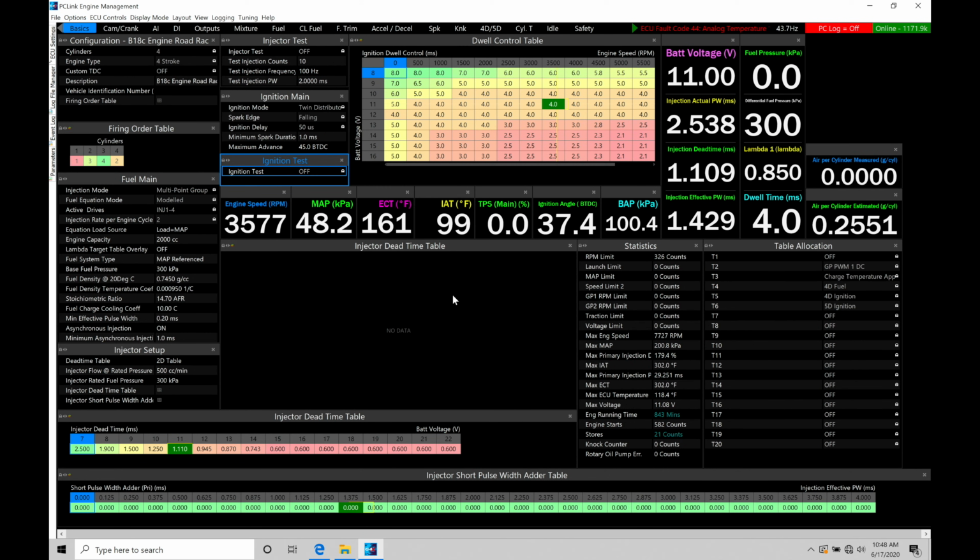So these failsafe protection features are in place so that the engine won't get damaged. We don't over rev it. We don't run too much boost on the engine. Now we can have additional things above and beyond the basic failsafe protection strategies that we have within our programming. We can also use things like our oil pressure protection or oil temperature protection, overheating protection for oil temperature, or our lambda lean protection. So we'll find that depending on what sensors we have wired into our G4x box, we can use those for logging purposes, but we can also use them for failsafe strategies.